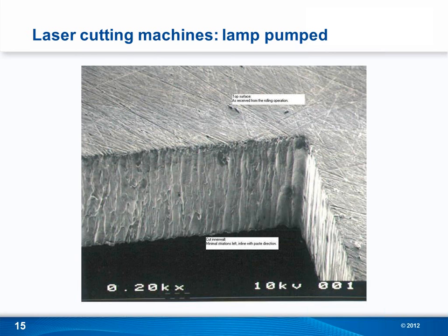The cut that is being made by the laser is very narrow. It's the width of the laser beam, and typically that runs between 20 and 40 micrometers. So the cut is much smaller than the aperture width, and when you're done with a single aperture, there's a piece of metal in the middle that gets blown away and disappears in the waste stream.